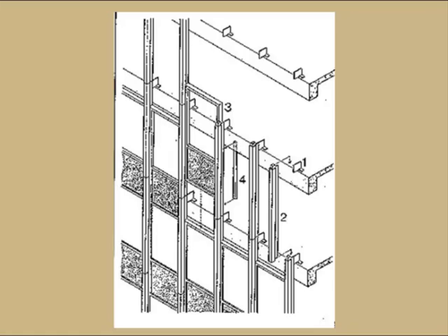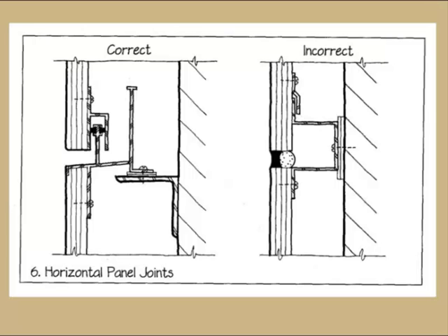And this is a really helpful graphic in showing how that's all put together. You can see there's anchor systems that actually secure to the structural framing of the building. Then you would have mullion systems that would run vertically. Then you would take some sort of pre-assembled unit, as Russ said, like glass or metal, lower that into the mullion system, and then provide some sort of interior trim. But there you have a system. It's totally framed to that building, and it's transferring all the gravity and wind loads to the actual building frame.